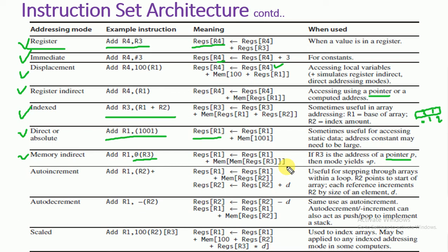For a pointer we use an indirection operator, right? Normally a pointer contains the address of another variable, but now the pointer contains the address of another address. That address will have a value. So indirectly we are accessing a particular element. The register has a memory value, the memory content of that register value, which is again an address. The content of that particular address will be retrieved and added with R1 and the result is stored in register R1.